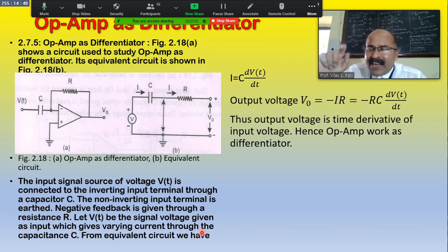Across the capacitor it varies exponentially with the time constant, that is e raised to minus t divided by RC, where RC is the product of the capacitor and resistor magnitudes connected in this circuit. Here C is the magnitude of the capacitor, that is the capacity, and R is the resistance, measured in ohms.